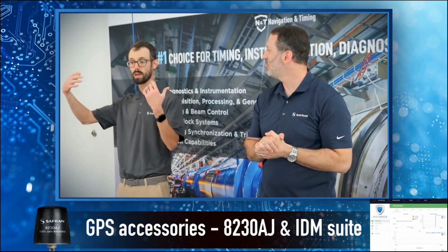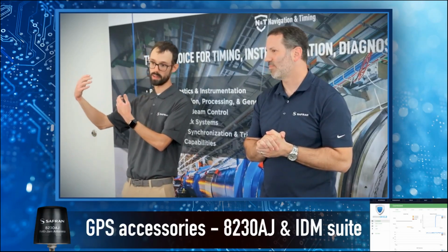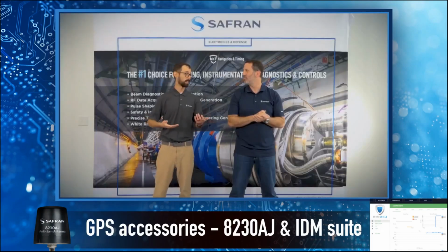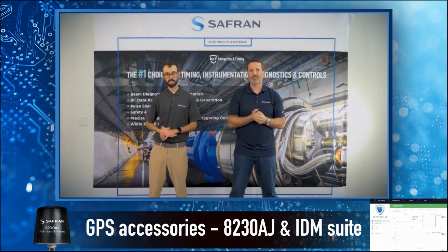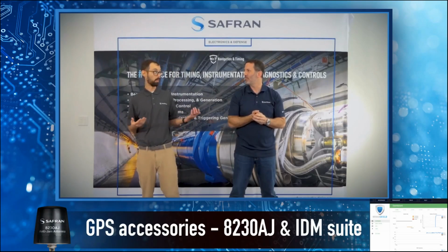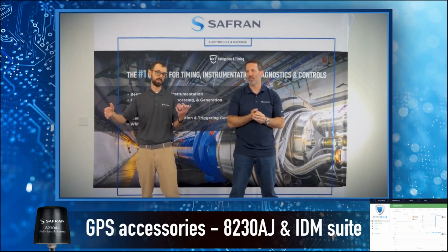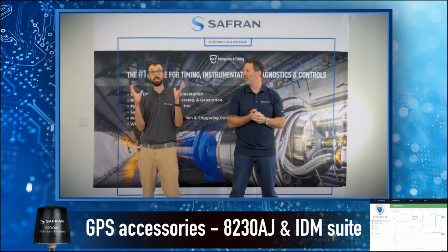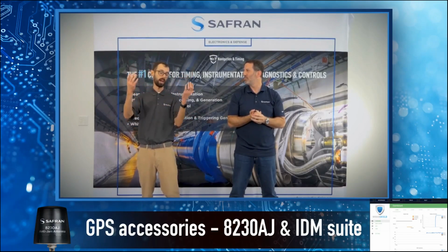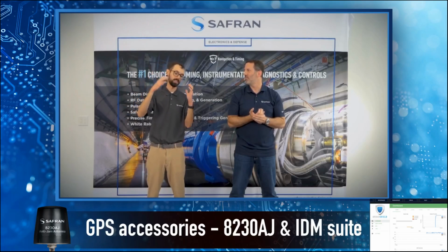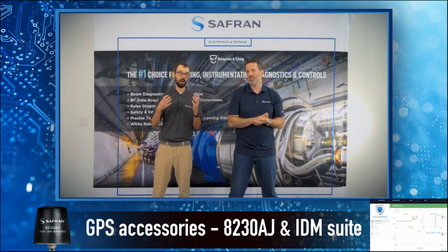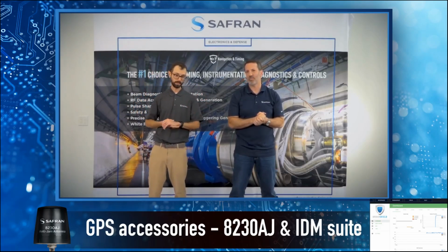It ignores terrestrial signals from 30 degrees of elevation and below, mainly because that's where most jamming and interference will be derived from, our terrestrial sources. So if our antenna is ignoring those, it allows it to then be receiving, hopefully, all live, valid signals.